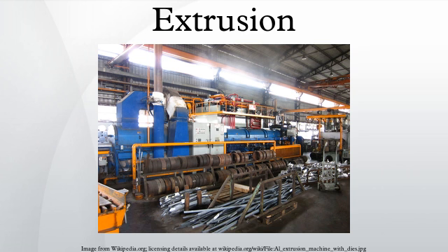Materials that are commonly cold extruded include lead, tin, aluminum, copper, zirconium, titanium, molybdenum, beryllium, vanadium, niobium, and steel. Examples of products produced by this process are collapsible tubes, fire extinguisher cases, shock absorber cylinders and gear blanks.